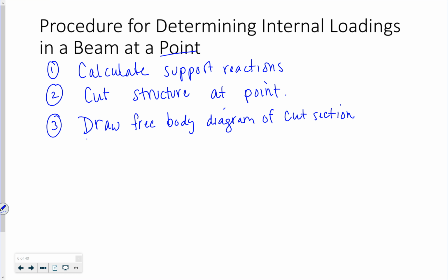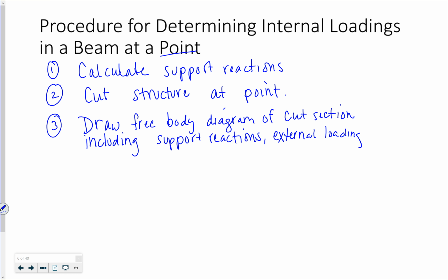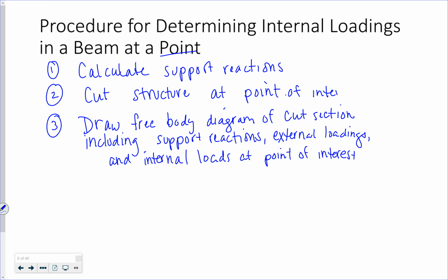And on that free body diagram, I need to include all applied loads, all support reactions, external loadings such as any applied loads, concentrated forces, moments, and finally the internal loadings at that point, at the point of interest. And then finally just solve for those unknown internal loadings.